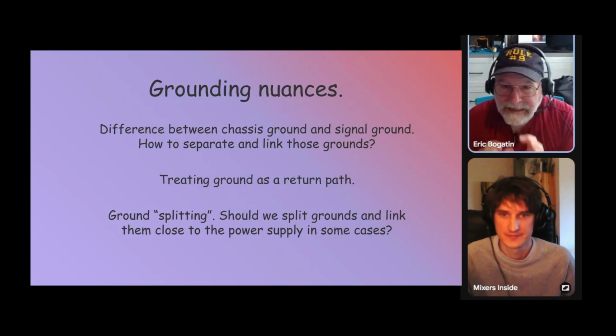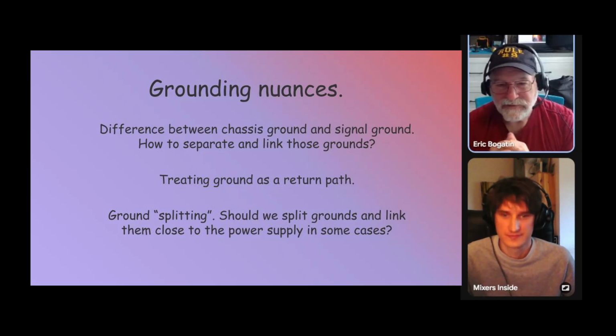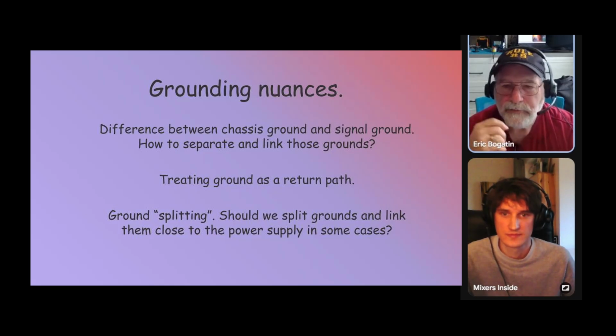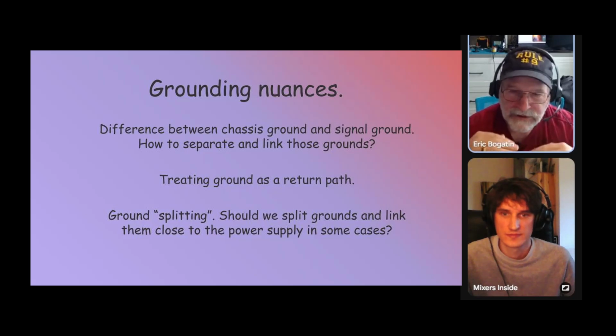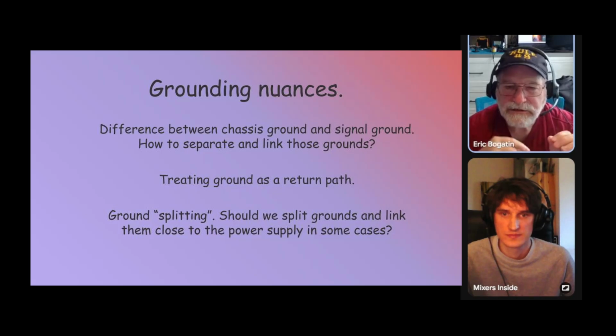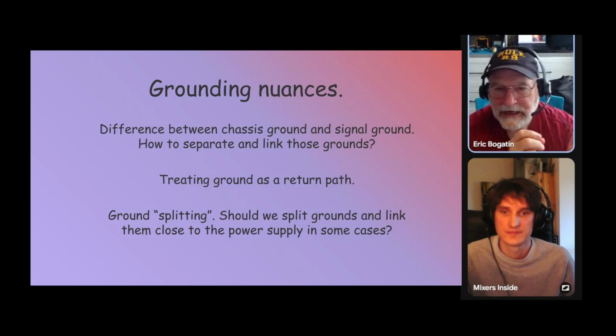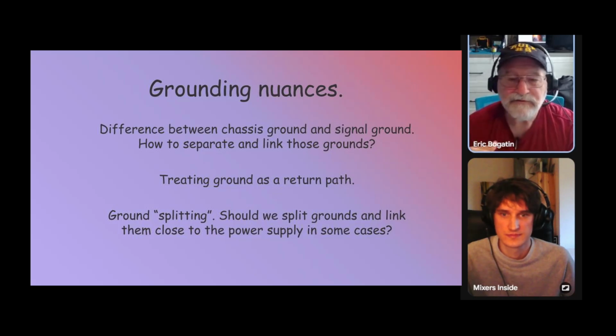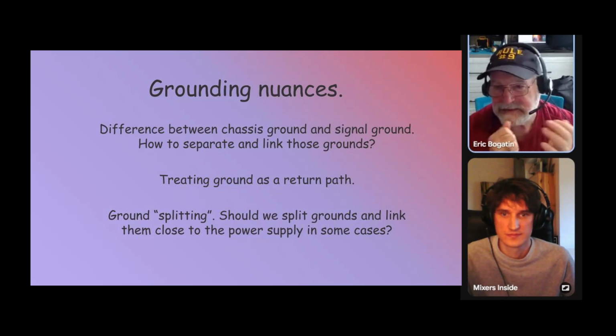If you're going to be really careful, it's a perfectly fine thing to do, but not every layout engineer is really careful. And you have to trace every signal line and make sure it doesn't cross that split. That's why I advocate using the solid return, but instead of using the return plane as your reference for low-level signals, treat it like a differential pair and carry the reference with you. That completely eliminates the risk of a signal crossing the split accidentally.